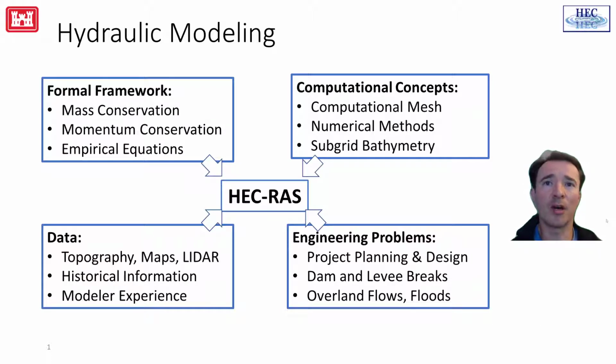As a hydraulic modeling software, HEC-RAS is involved with aspects of other areas such as fluid mechanics, data processing, and engineering. This presentation will cover the conceptual framework of HEC-RAS, emphasizing hydrodynamic concepts like mass and momentum balance, friction, and turbulence. Computational concepts, including the mesh, numerical methods, and subgrid bathymetry, will also be covered in detail.